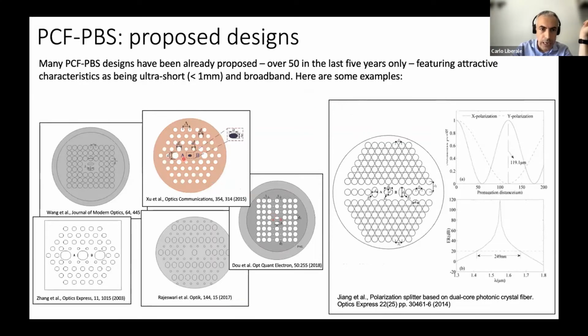Typically, where you see A and B are the two cores, because the two cores are basically a coupled system of two birefringent waveguides, which induces at some point a change of trapping. Basically, you segregate one polarization in one core, and the other polarization in the second core at the right length of the structure, and you implement this polarization beam splitter.